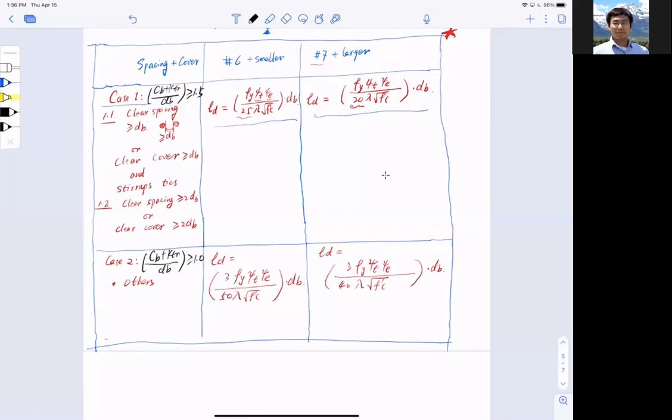That means if I calculate using the two approaches, you will find that the development length computed using the simplified approach is always larger than or equal to the basic approach. So this will be more conservative, and in a nutshell, longer. You sacrifice your length for speed. All right, that's about as dry as this lecture can get.